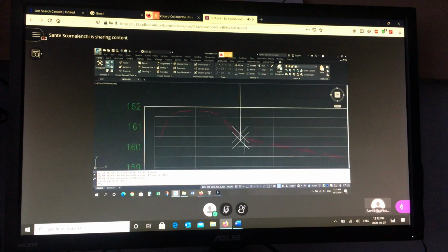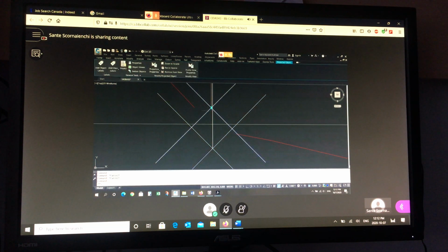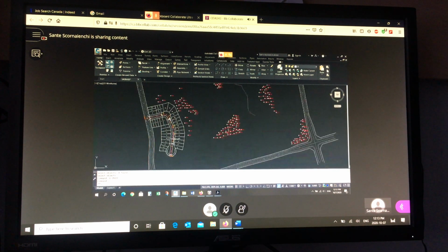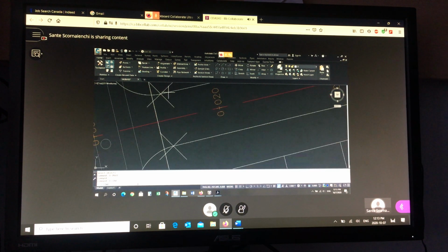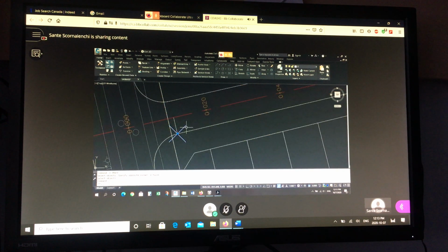Say OK. And now, if you look at the profile, you'll see, oh, this one is further away from the intersection than this one, so I'm going to throw this one away. That's my station for the low point. It's easier to see in profile. If you just project both, you can quickly see here which one is further away. It doesn't matter which side of the road, whichever one is furthest away. If you want to draw the two lines that I had before, right, if you want to draw a line from this end point perpendicular to center, or this end point perpendicular to center, and decide, yeah, it's this one, I won't even worry about that, and then just project the one, you can do that.